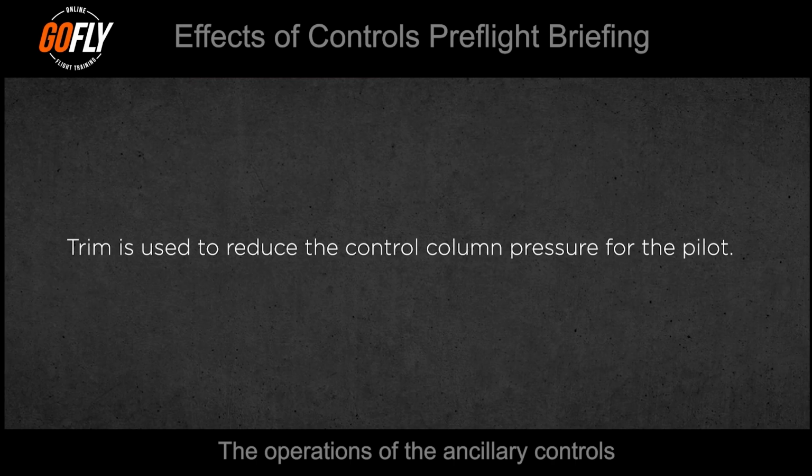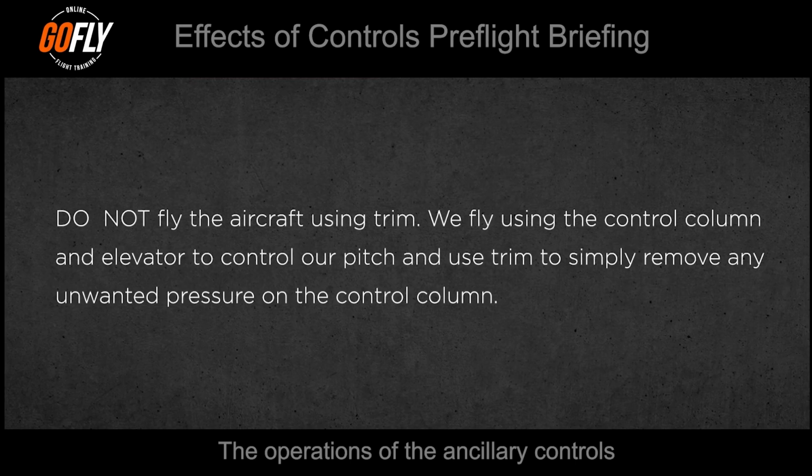Trim is used to reduce the control column pressure for the pilot. Remember, do not fly the aircraft using trim. We fly using the control column and elevator to control our pitch and use trim to simply remove any unwanted pressure on the control column.